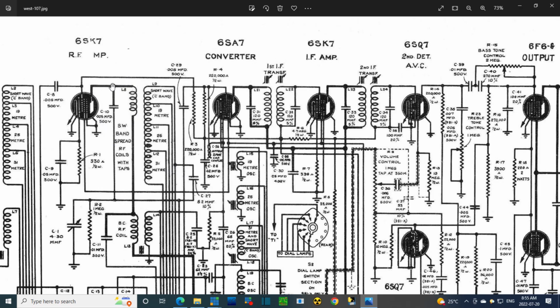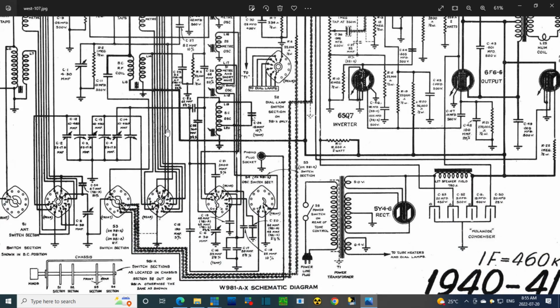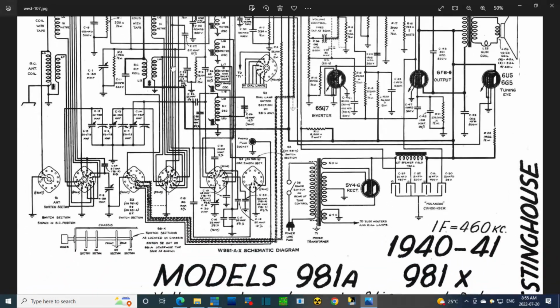And the reason is one leg is tied to a coil, like that, and the other leg is tied to a switch. If you come down here and follow these lines on the schematic, it's a big long line here. But in the actual radio, it's direct. The switch connection point is this one here, number 2. That's from the peak down 2, and that matches the position on the switch wafer, and it's the right switch wafer. So I mean, it's all adding up.